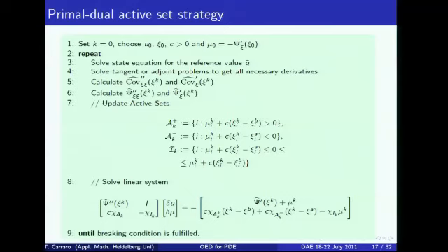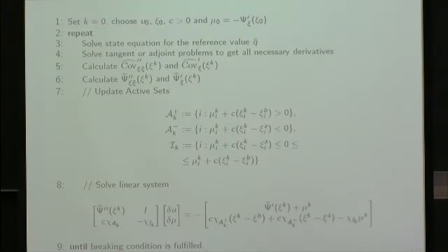So here we have a cycle where in each cycle we have to solve a linearized problem, exactly like in Newton. For doing this, we have to solve the state equation, and as we have to do with the covariance matrix, of course we have to do with sensitivity, so we have to solve the sensitivity or an adjoint problem. If you use a sensitivity, you solve as many linear equations as there are parameters. With an adjoint approach, you just solve one of these problems.